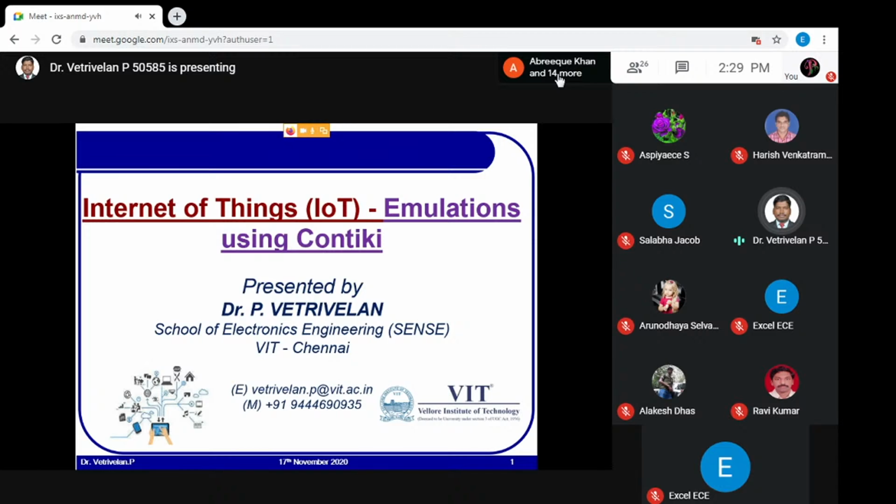With respect to IoT operating systems, we have Contiki, TinyOS, Linux, RIOT. Contiki is so popular, and we have a lot of open source support in the market, with its consumption of RAM and ROM, and many features like support of C, C++, multi-threading, and MMU, memory management unit, with respect to microcontrollers with or without that support, modularity, and real-time services.